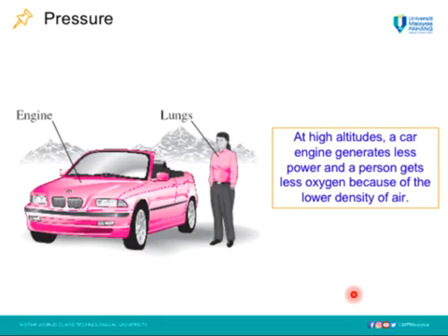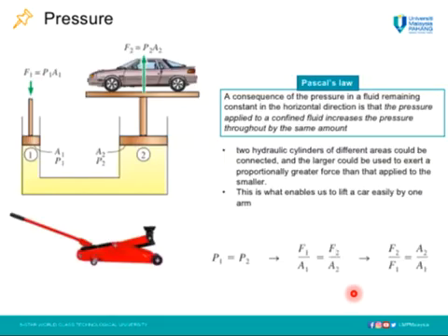Similarly, a 2.0 liter car will act like a 1.7 liter car engine at 1,500 meter altitude because of the 15% drop in the pressure and thus 15% drop in the density of the air. The lower pressure and thus lower density also affect lift and drag. So airplanes need a longer runway at high altitudes to develop the required lift, so that they can climb to very high altitudes for cruising in order to reduce drag and thus achieve better fuel efficiency.